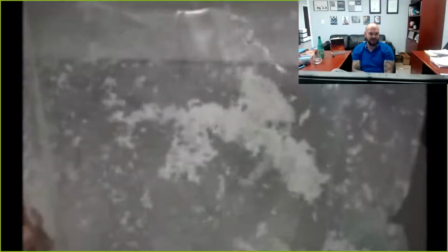Now, anybody that's pouring nickel, aluminum, bronzes and ferrous alloys will always have these great big, large, disgusting defects in the cope side of the casting. Those are agglomerates of millions of little oxides, and this is the morphology, or how it takes place. You guys can see this video, Jerry?